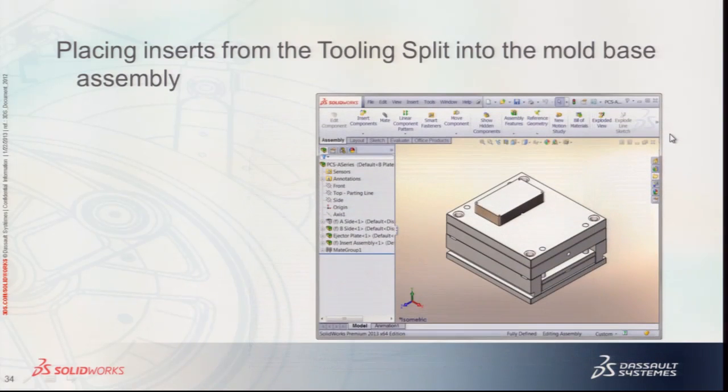So the next step, of course, is to take that insert assembly and place it actually into your main assembly, as you can see right here. And I like to use the distance mates to locate it. And then I delete it and fix my component there, and that just makes it easier for our next step, which is clicking and dragging and dropping those components from your insert assembly into the individual assemblies.